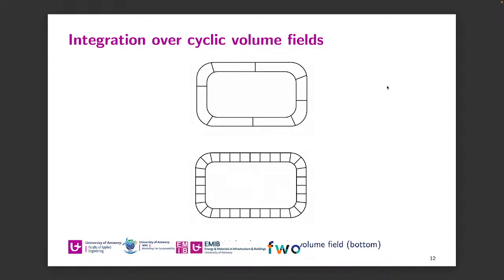What we saw was that when we use a very coarse volume field, meaning only 1 volume per pipe, 1 volume per radiator, the irregular field was still the dominant method, because you have to do a lot of calculations, but only on a few volumes, so the transformation is a dominant calculation there. But when we did it on a finer grid, so when we use a lot of volumes per pipe, then this method took less time.